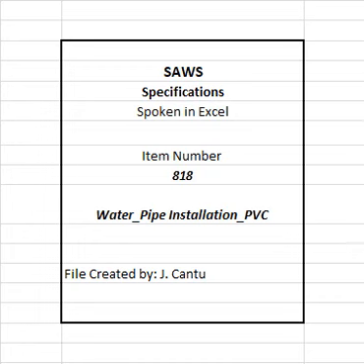818.4 Materials. The materials for water main installation shall conform to the specifications contained within the latest revision of SAWS material specifications. 1. Material specification item No. 113-03, specifications ductile iron restraint joint fittings for use on ductile iron and polyvinyl chloride pipe. 2. Material specification item No. 95-10, pipe joint restraint systems.